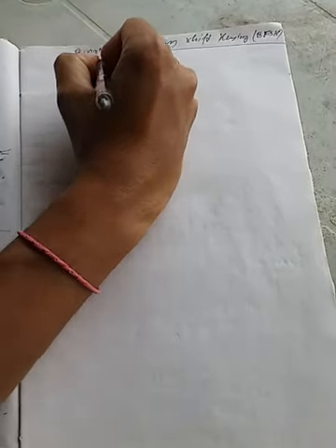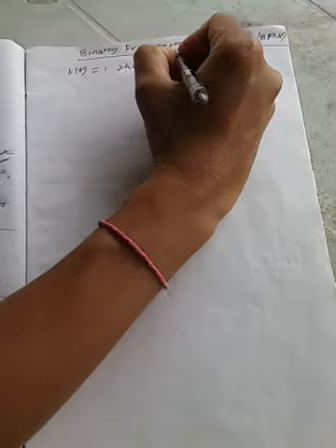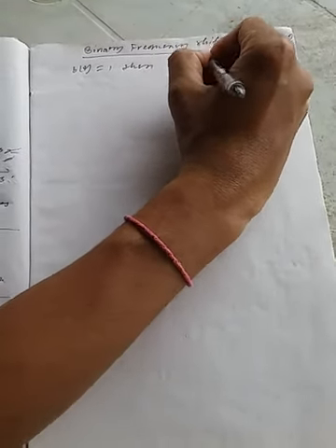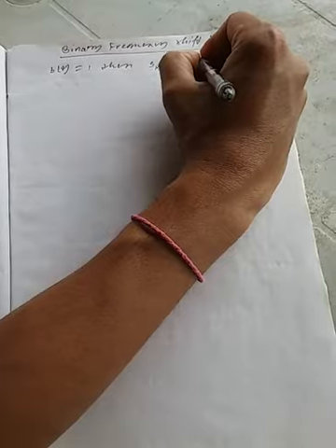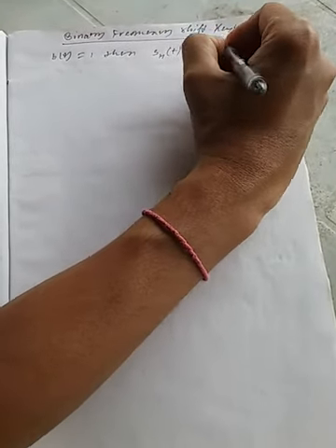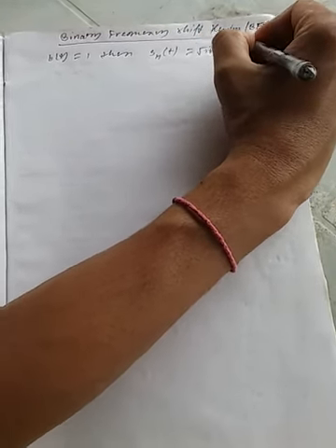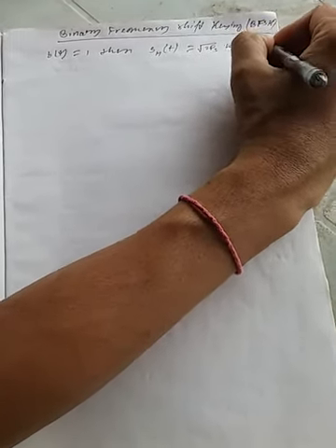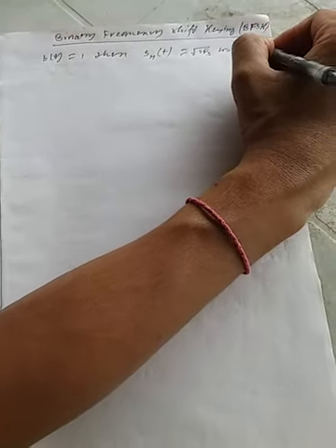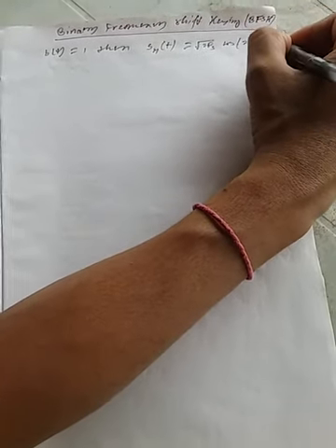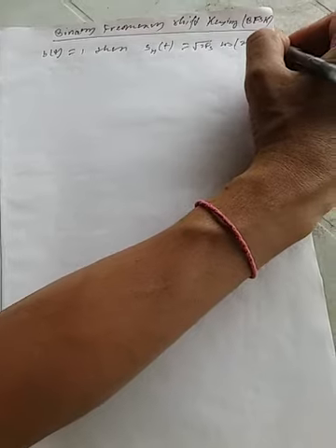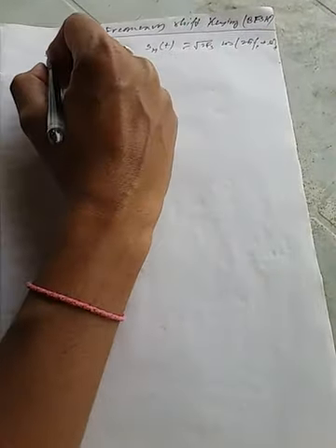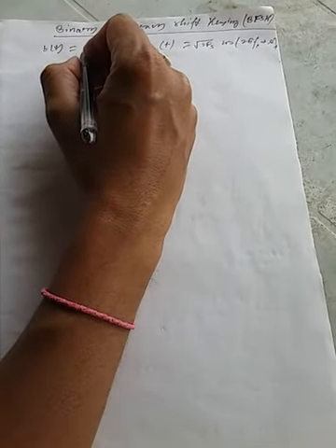When b(t) is equal to 1, the high frequency signal, represented by SH(t), will be equal to root 2 Ps cos 2 pi (fc plus omega) t. Fc is basically the carrier frequency, and it is shifted by omega. So this is for the symbol 1.